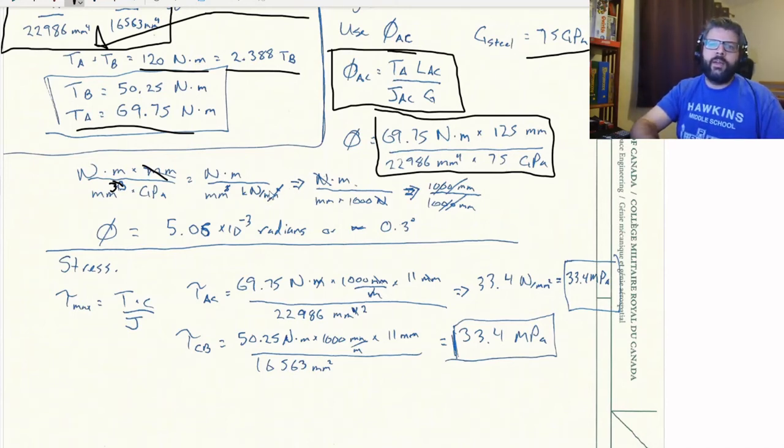So subbed in that and then canceled out 2 more of the millimeters on this term. Leaves us just a 1. So we got Newton meters per millimeter. And then, Newton meters per millimeter kilonewton. So subbed in 1,000 newtons for the kilonewton, crossed out the newtons. That left us with meters per 1,000 millimeters.